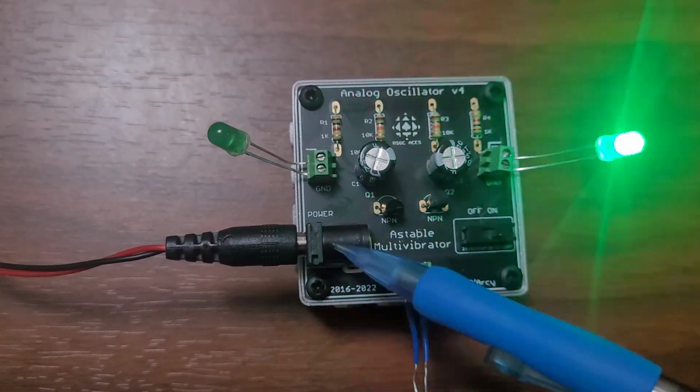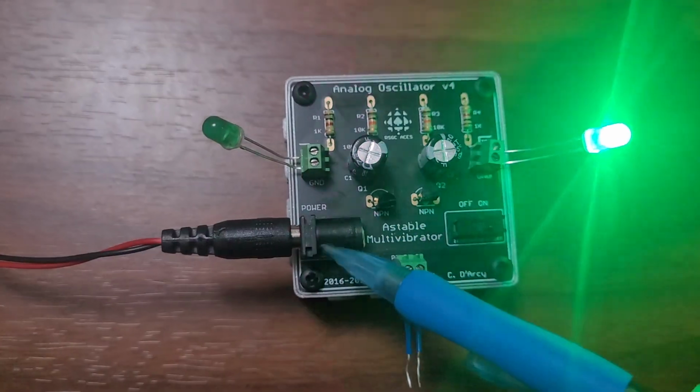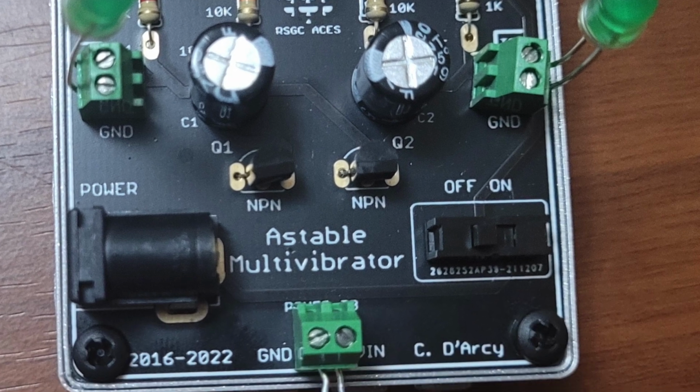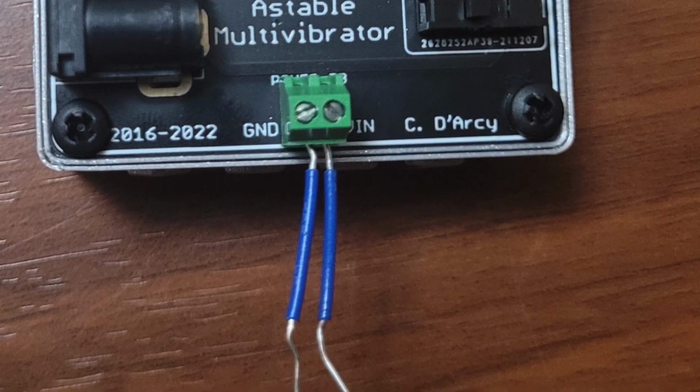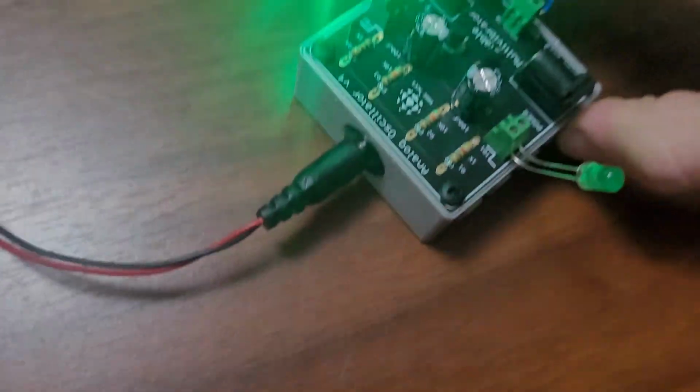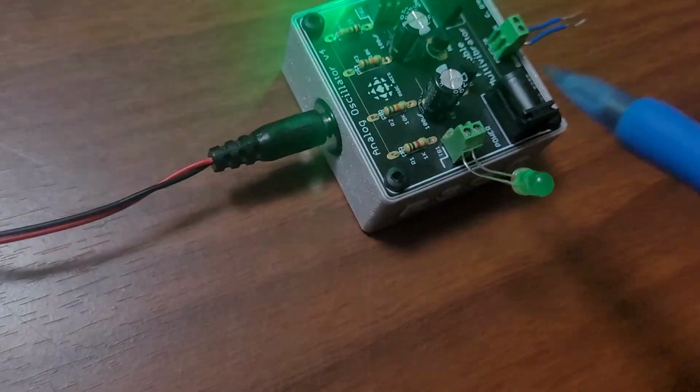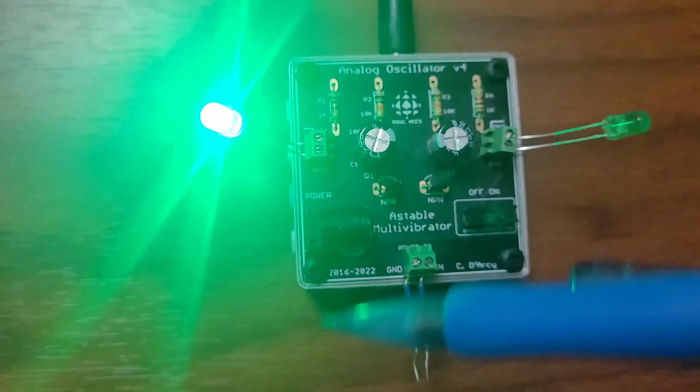Then, the PJ-202AH power jack was soldered to give it another way of reaching power. After preparing the PCB circuit, the PJ-202AH power jack was also soldered onto the shorter jack inside the case to give it an alternative power source. Finally, screws were used to place the PCB into the case securely.